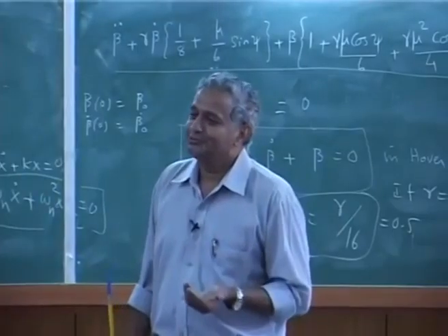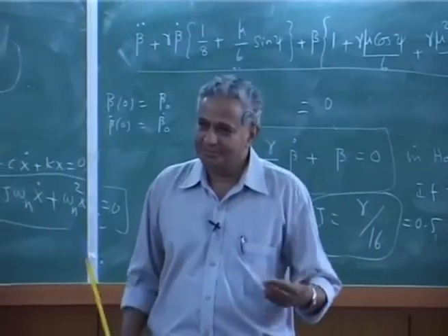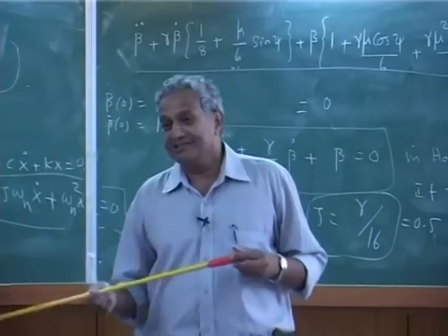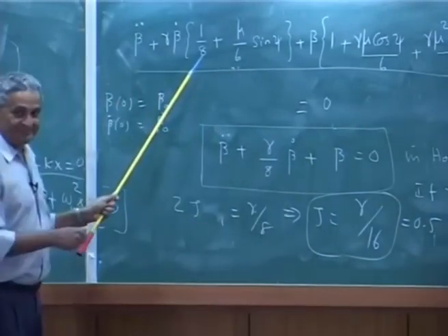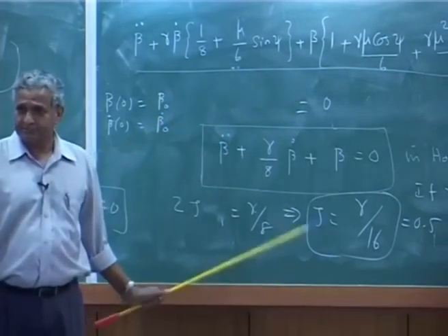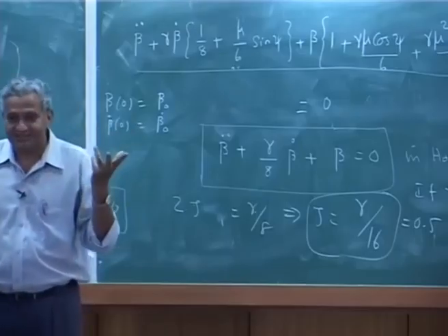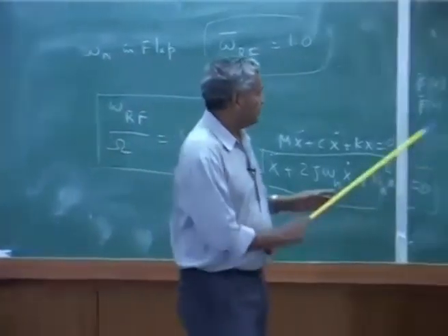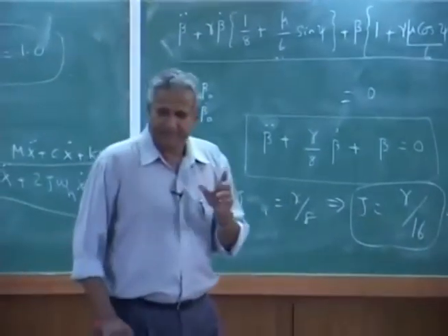But you don't go to that value of mu in helicopter blades, because helicopter blades operate below 0.4 maximum. That kind of tendency comes with a high value of mu. So I will give you one problem which you are going to do numerically. This is an ordinary differential equation, only with time varying coefficients. How will the solution look for different values of mu, for given initial conditions? I will send it with the assignment today. You analyze it, you plot it, you will find very interesting things.